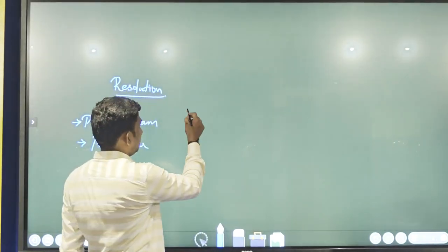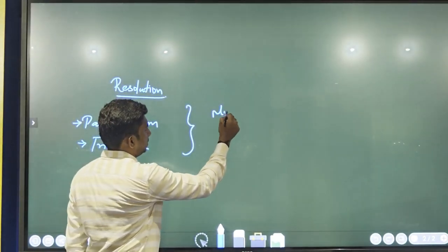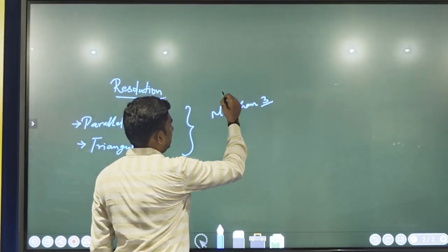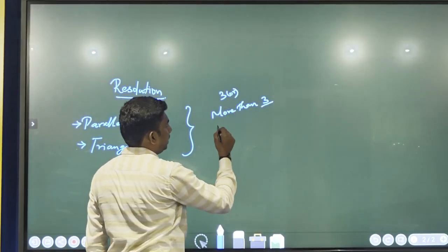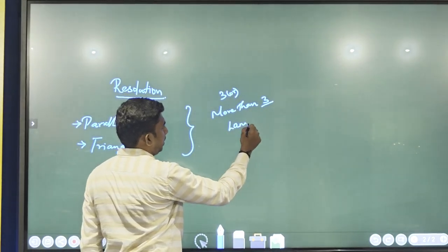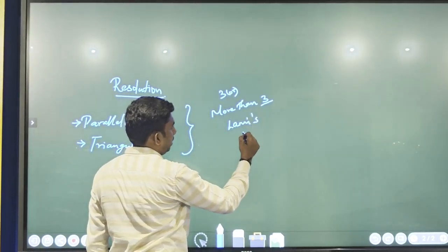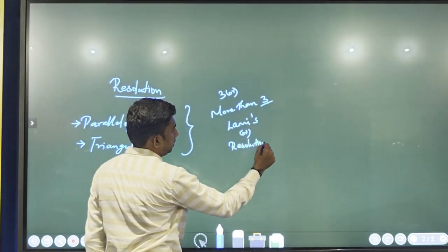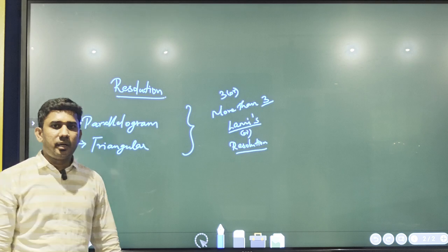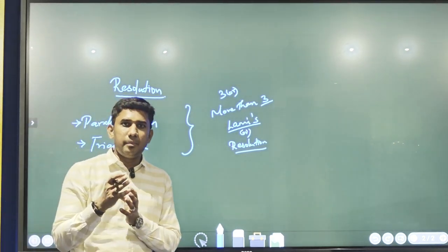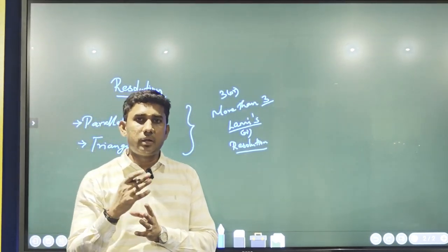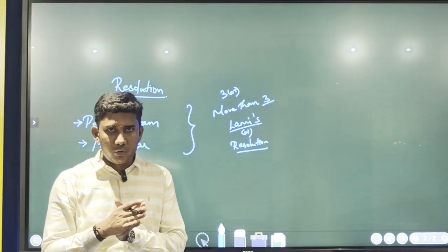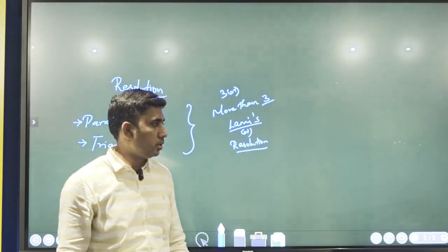If I have more than three forces, I can go with resolution of forces, and if it is exactly three, I can go with Lami's theorem. So we should understand in which situation Lami's theorem should be used and in which situation resolution should be used. We can cross verify the answers, so that we will get the same answers whether we go for Lami's theorem or resolution of forces.